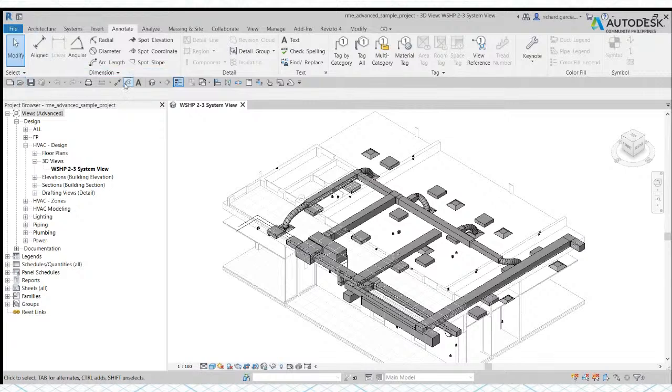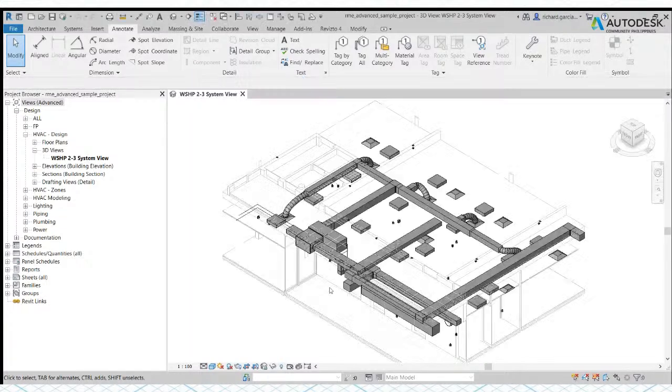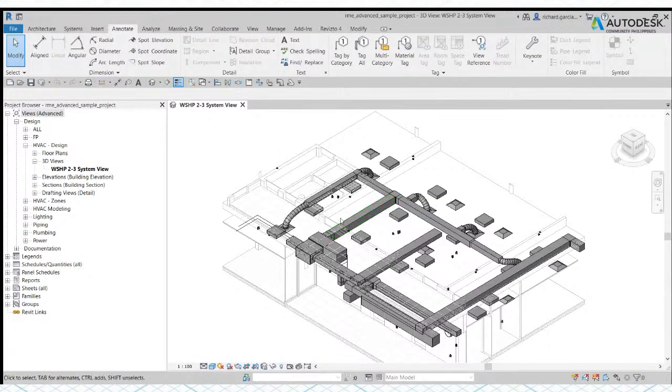I just put it here below. But if you want to put that back, you can click the arrow there and select Show Above Ribbon. Just click that one and you will now be able to place it. This is the original location of your quick access toolbar. But on my part, I always put it below. Show Below the Ribbon. Okay, so that's my quick access toolbar.